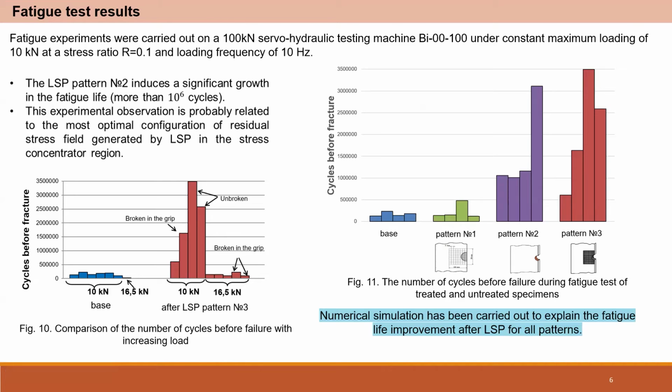And we understood that the first pattern didn't give good improvement, in comparison with the second and the third pattern, where fatigue life was increased about 10 times. After that, we decided to use numerical simulation to estimate what residual fields we received after these patterns.